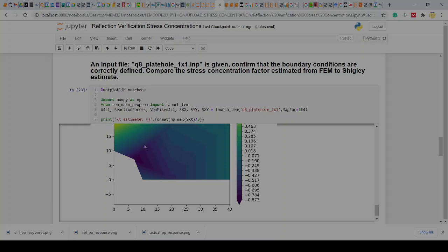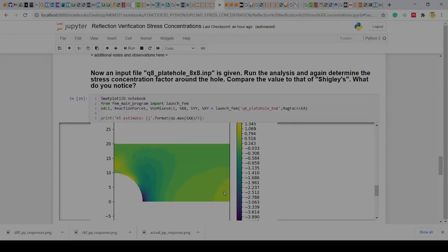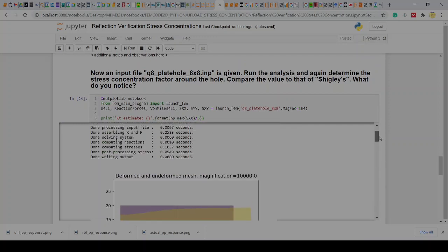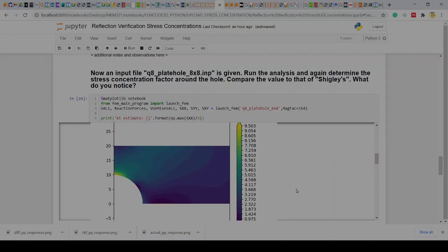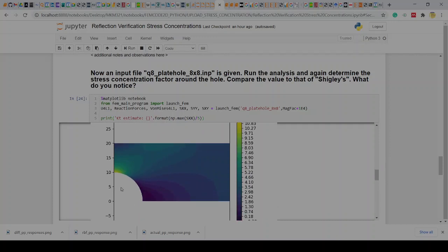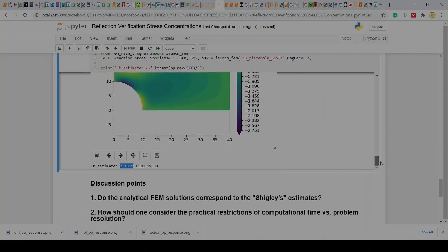So please take note that if you have stress concentrations and you need to resolve them, you really need to make sure that you have enough elements to resolve that complex stress field. Maybe I'll leave you with this kind of variation. The variation in the stress field here is quite a lot. There's not a lot of variation here compared to what's going on there. You can see very quickly it's very high and it goes down. So we have large variations typically in stress fields, and that's really where you want to add more elements. It's not about the value, but the variation. Where the variation is quite mundane, you could get away with a much coarser mesh and still be fairly accurate. So that's just to give you some ballpark.